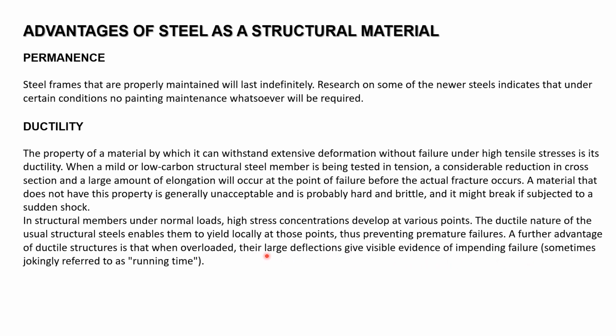This is very important because structural members under normal loads can develop high stress concentrations at various points. A material that does not possess this property is usually not acceptable. Most probably it would be a brittle material that would break if subjected to a sudden shock, or if a sudden load is applied.